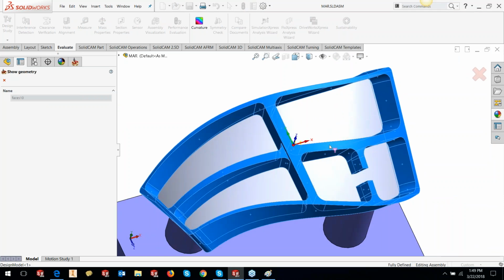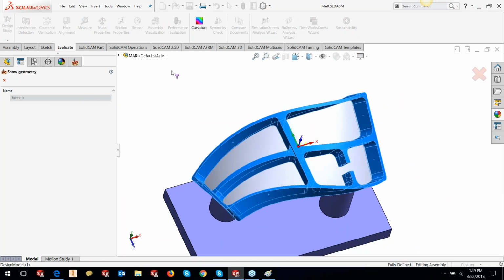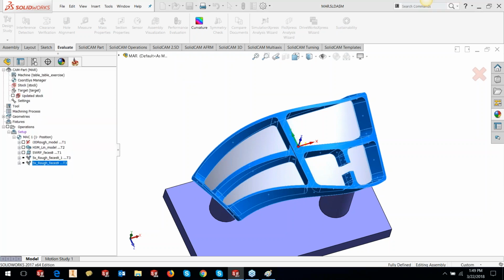You can give them a different color and select them. There is another possibility: you could select the entire model, including the floor surface, as the wall surface. The software is pretty intelligent. It understands that the floor has already been selected, eliminates the floor surfaces from the wall surfaces, and keeps just the wall surfaces needed for machining.